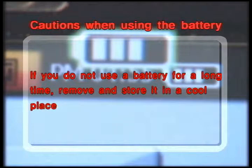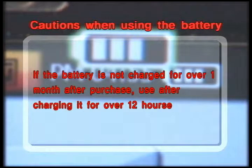If the product will not be used for a long time, take the battery out before storing. Furthermore, if the battery is not charged for over a month, use it after fully charging it for over 12 hours. If the battery is not used after it is charged, it will gradually discharge by itself, so please charge it right before use. For other information regarding charging the battery, please refer to the manual.